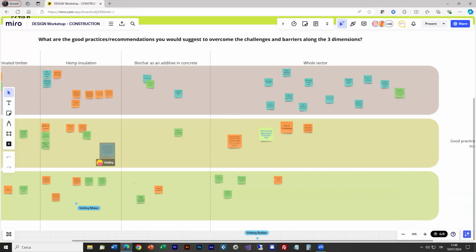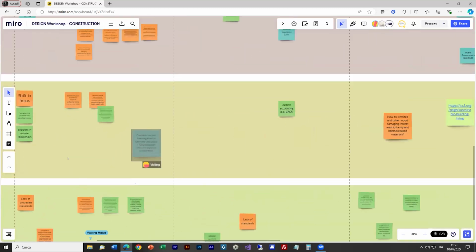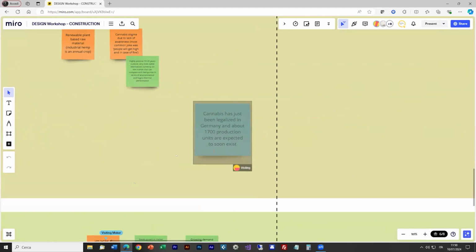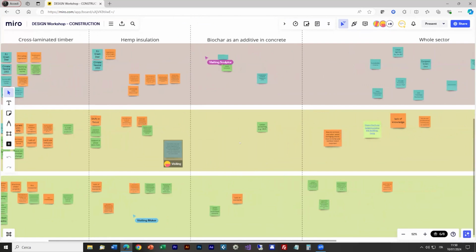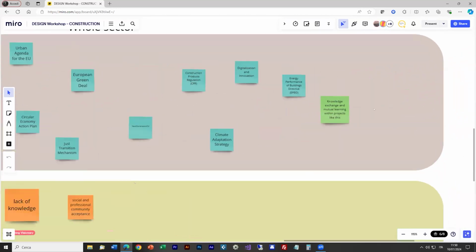The other thing, with regards to the presence of glues, is that the percentage of glues in relation to the mass of the component is actually minimal. We are talking about less than, I think, 2%. But the key point is that in the worst case scenario, if we have a glulam beam or a CLT component, it is incinerated to create energy, but it could also be transformed back into the original lamellas which were used to create the timber itself. It's not an easy process, but it is something that could be foreseen. But again, the best case scenario is one-to-one reuse or a minimum amount of remanufacture for the components.